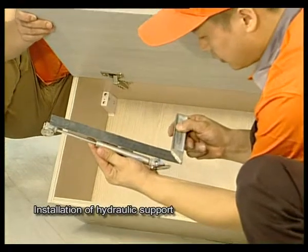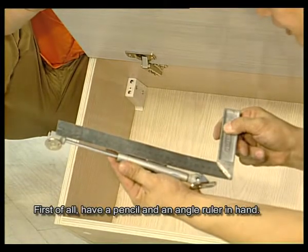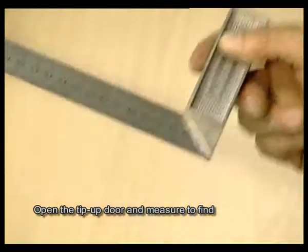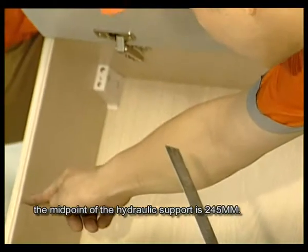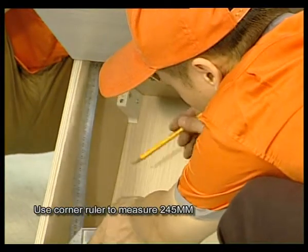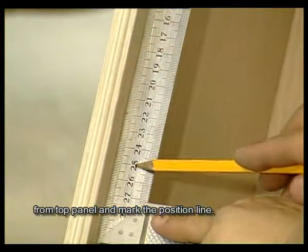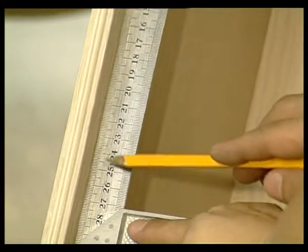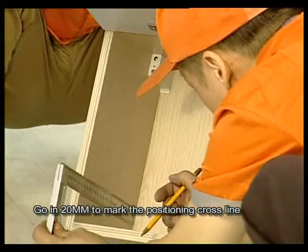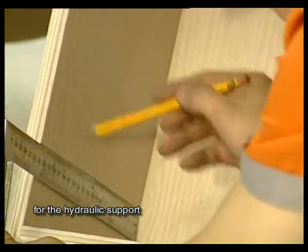Installation of hydraulic support. First of all, have a pencil and angle ruler in hand. Open the tip-up door and measure to find the midpoint of the hydraulic support is 245 mm. Use the corner ruler to measure 245 mm from the top panel and mark the positioning line. Go in 20 mm to mark the positioning line across the line from the hydraulic support.